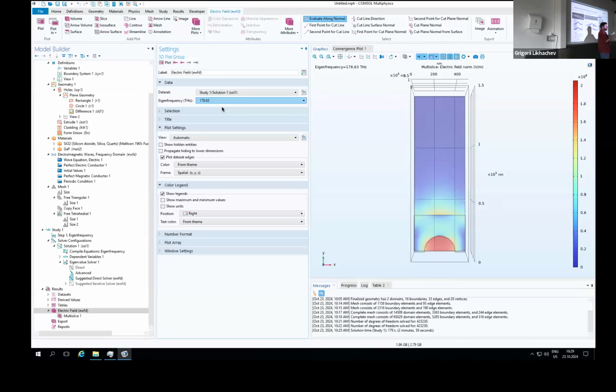It's like trying, by FDTD, to maximize the reflectivity by using this type of weird structure. It's hard to fabricate, because if you simulate something, it should be exactly like that. But with this method, often you have very small holes to pattern. It's not very reliable, and also they didn't get very good quality factors. Sure, they used a few unit cells. Is it good? I mean, it's something, you know.